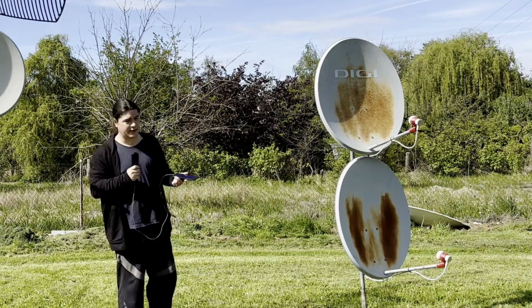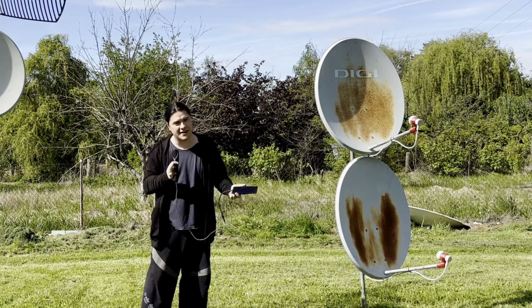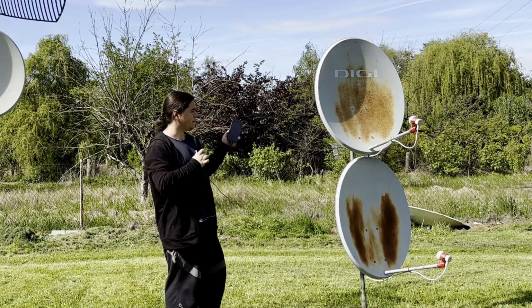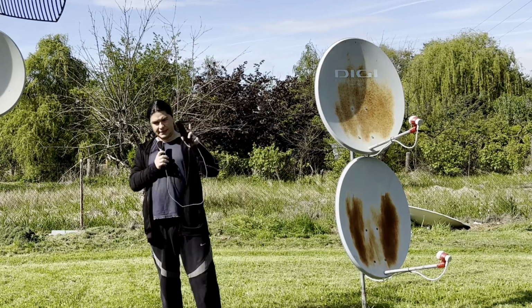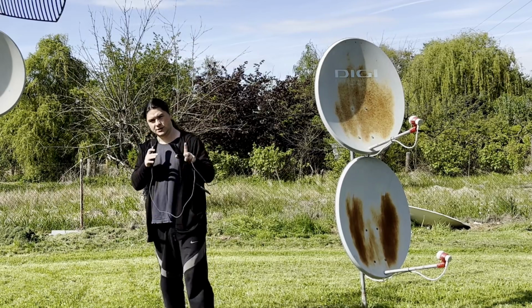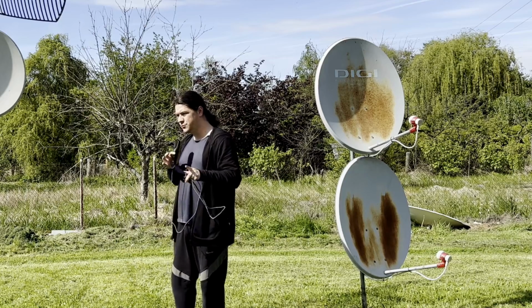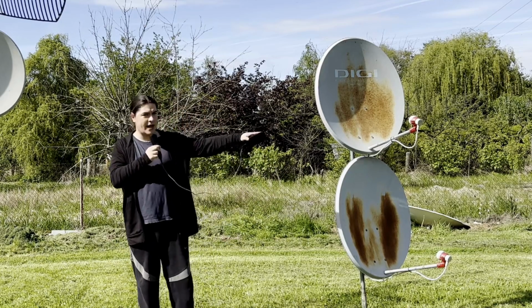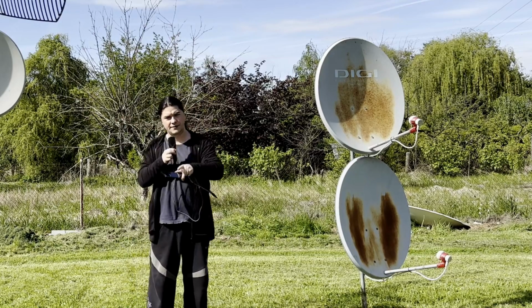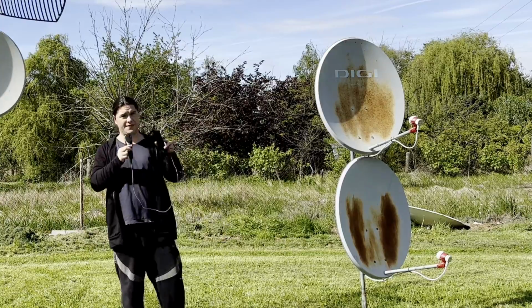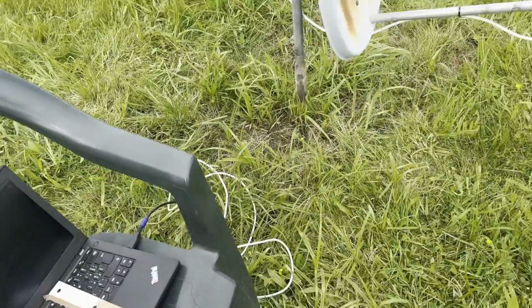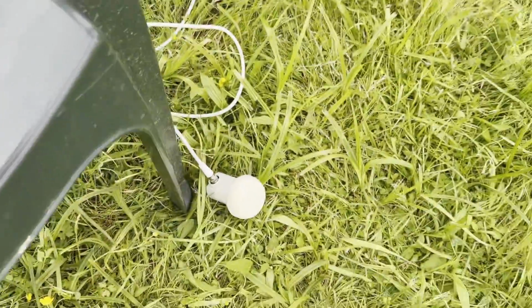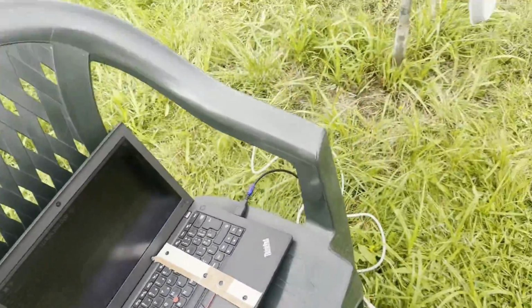The other thing, the second most important thing after having line of sight with a satellite, is having an antenna. Now, this satellite, the downlink, at least on the narrowband transponder, is so stupidly strong that you can just take the LNB from the dish antenna, aim it directly at the satellite, and I believe I have actually done that in the clips that I'm going to be showing, and that is enough. I think at one point I just dropped the LNB on the ground, and it just happened to land in an orientation that was enough to see the beacons coming through the transponder.